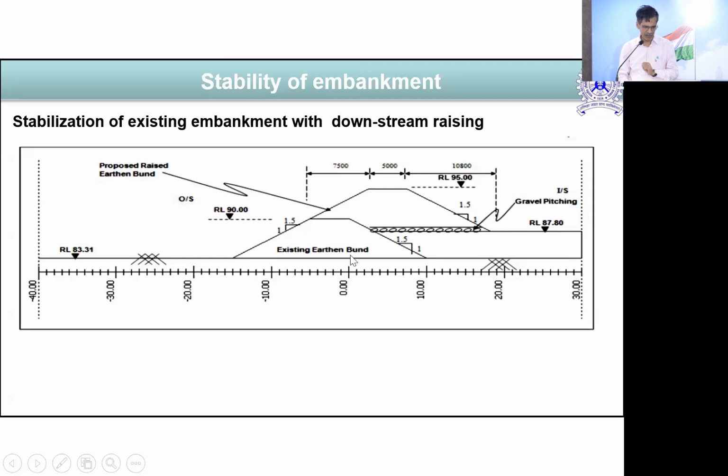Now what I will do, I will go with this one. This is the type of picture. So with this picture or geometry, I am first envisaging that my dam will look like this. Like Dr. Panda said, we are doing all in two dimensions, and this geometry should be the most critical geometry, where the slope is 1.5. And suppose the maximum water table is going here, so that's the section I have to consider.